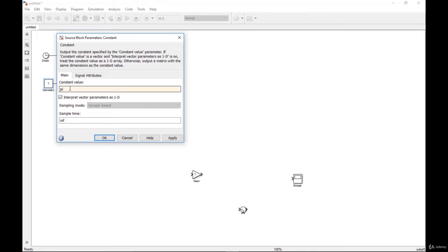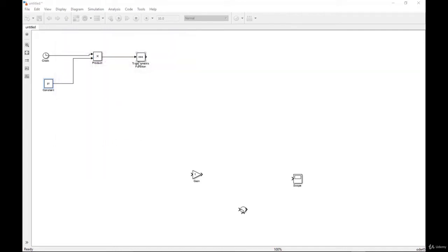I do so for constant. Because the simulation time is 10, I enter it in the clock too, which is 10 by default. We set the constant block P, so cosine multiplies to a gain, which the amount of gain is 6. The cosine is prepared now.